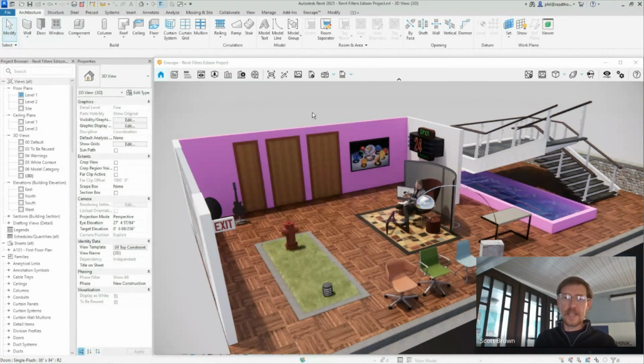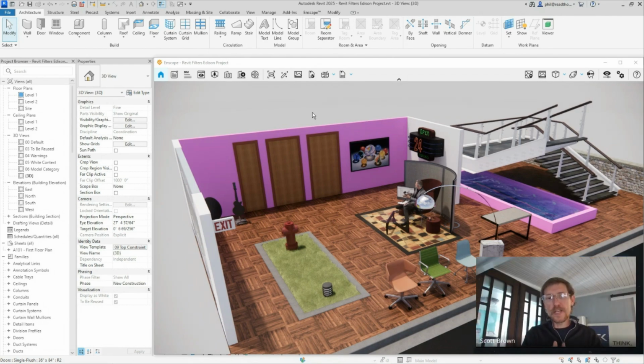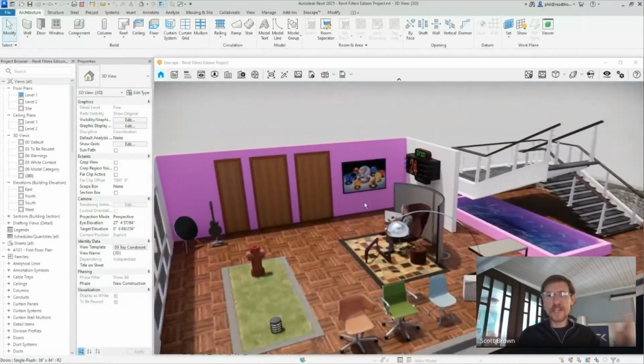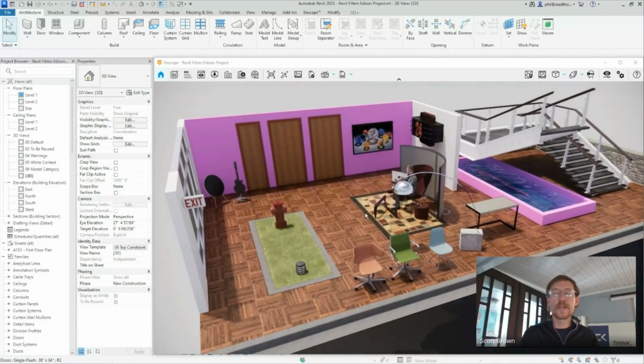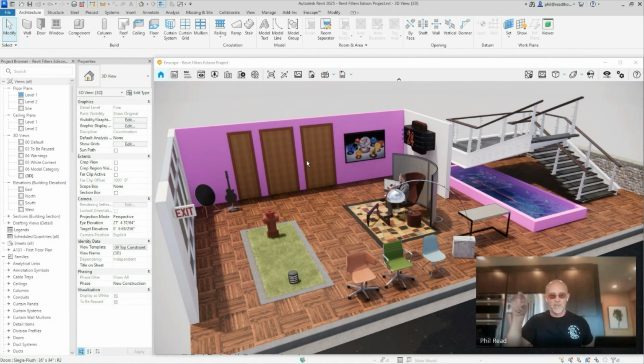And then the other filter that I'm not sure if you're going to show that's very similar. Do you prefer to attach top and bottom, so that it's attached to the slab underside, or do you attach it to a level? No, we don't ever attach it. Never attach. If you know your floor thickness, so every wall in level 1 goes from level 1 up to level 2 minus 5 1/4 thickness, if that's your composite slab assembly, and that will give the true unconnected height. The only time you will attach is if something's sloping, we'll attach it. Right. If it's got some kind of circuitous pattern at the top. So otherwise you don't attach, and you identify it with a parameter.